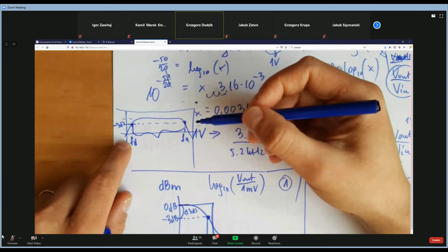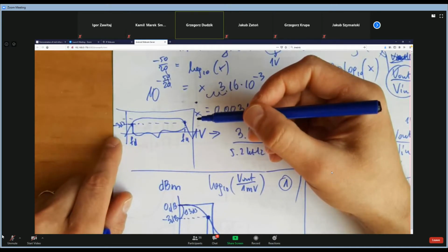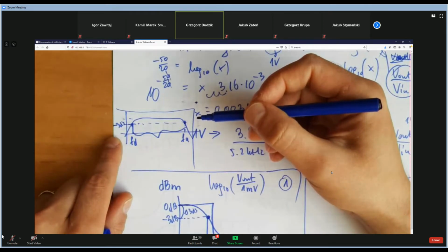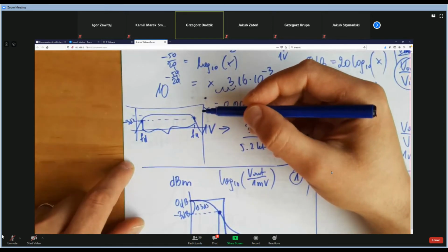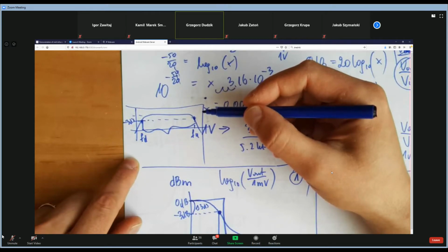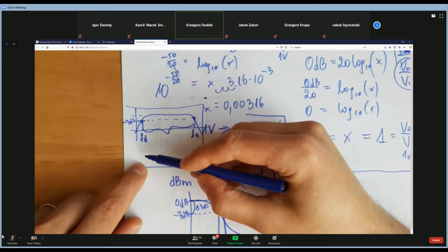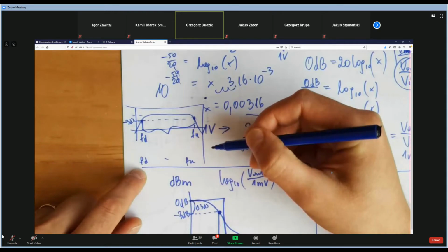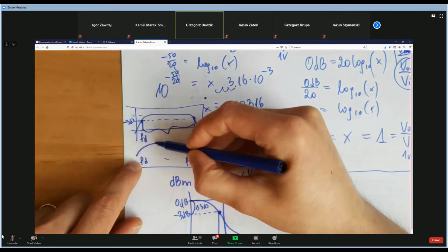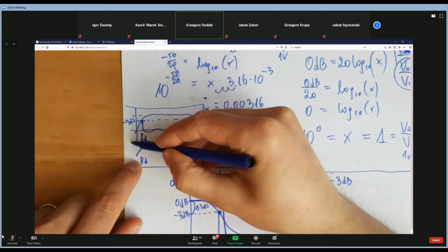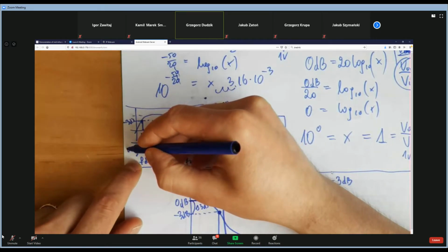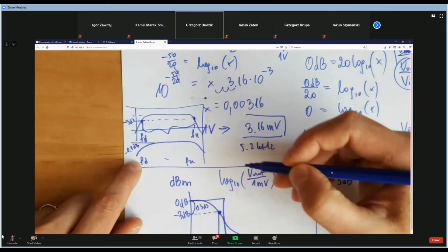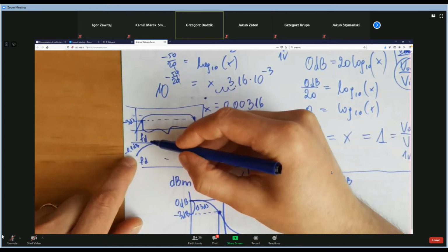But if I talk about audio amplifiers, sometimes we can buy a very nice amplifier which is named hi-fi equipment. Hi-fi amplifiers have the bandwidth described like the F down to F up frequency, but not for signals which drop by minus 3 dBs, but for a drop of 0.1 dBs. 0.1 dBs is a very low drop of the signal amplitude.